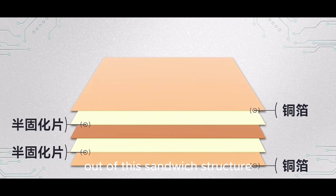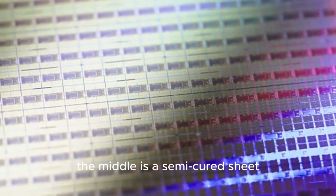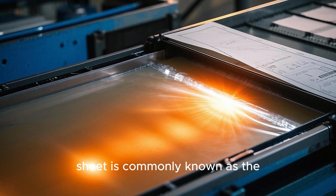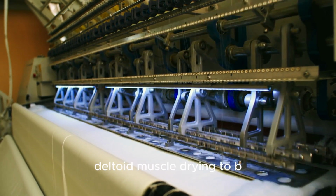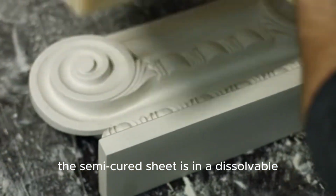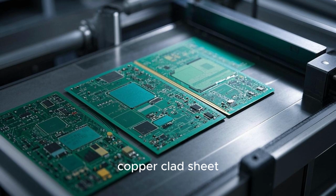It is split into a sandwich structure: the upper and lower copper foil, and in the middle a semi-cured sheet, commonly known as the connection sheet. It is fiberglass cloth dried through the gluing process to become the connection sheet. That is, the semi-cured sheet is in a meltable state and will be used to directly press the copper-clad sheet.